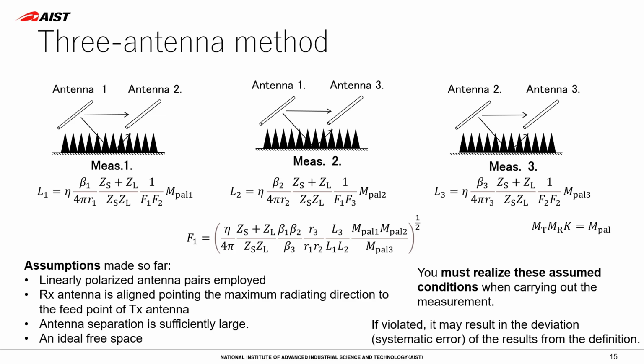When a calibrated vector network analyzer is employed in the measurement, the source and the load match can be considered to have been corrected to be negligibly small. In this case, loss becomes attenuation. So, the site insertion loss is called site attenuation. In EMC measurement and site evaluation, site attenuation has a different meaning. It is the minimum attenuation when one antenna is scanned over a specific height range above a conducting plane.